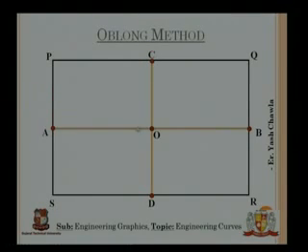So we will start. First I will divide OA into 7 equal parts, that is 1, 2, 3, 4, 5, 6 and 7. As you can see, it appeared. And then I will divide OB into 7 equal parts, that is 1, 2, 3, 4, 5, 6 and 7. Then I will divide PA into 7 equal parts, that is 1, 2, 3, 4, 5, 6 and 7, as you can see, as they are appearing on your screen. Then I am dividing QB into 7 equal parts, that is 1, 2, 3, 4, 5, 6 and 7. So I have these points.